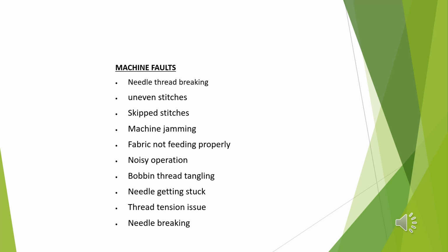Finally, we will look at needle breaking. It's caused by incorrect needle type for the fabric, a bent needle, or incorrect needle insertion, and can be corrected by using the correct needle type, ensuring the needle is not bent, and inserting the needle properly.